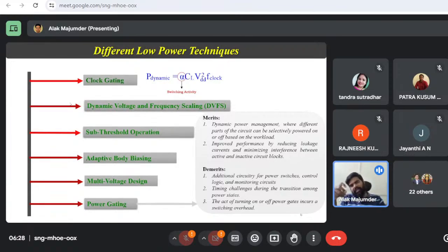So power gating has that problem, because in a flash of a moment we are turning it on, the change of current, di/dt, is huge. And I'm sure if you are comfortable with power electronics, you might have heard about L di/dt noise, right? In any communication from VDD to core, there are some RLC lines I'll discuss.